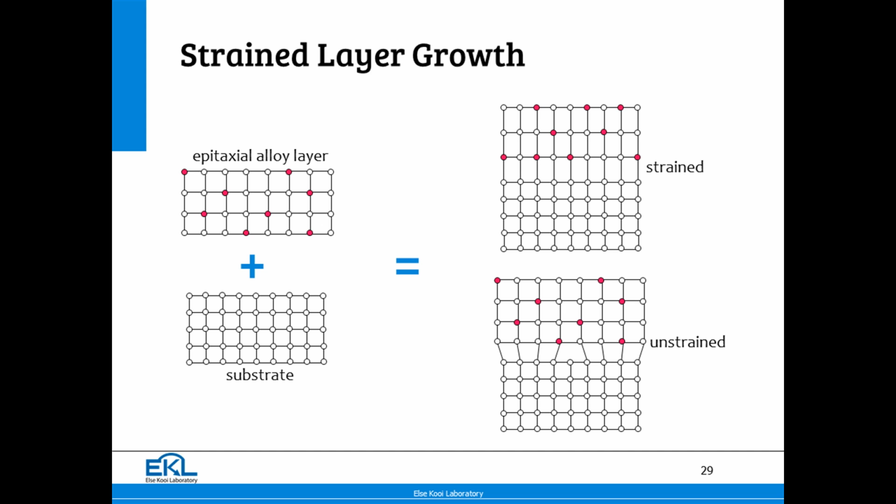And it's, well, not completely unstrained, but it relaxes. Let's try to draw it a little bit here. Here the lattice constant in the horizontal plane is the same as from silicon. If it relaxes, it expands, and at the same time forms misfit dislocations.